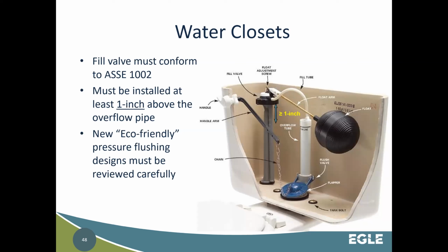But there's supposed to be a 1 inch gap from your fill, because this is how toilets fill, right? It flushes. This is your fill tube until it shuts here. There's supposed to be a 1 inch gap between the fill valve here and then the drain valve pipe here. I would be curious to know how many people actually open the back of a toilet and inspect this. My guess is probably not very many. I just had to rebuild a toilet at my vacation home. I made sure it was 1 inch straight up till I worked here. I never knew that. I didn't know it was 1 inch on the back of the toilet.